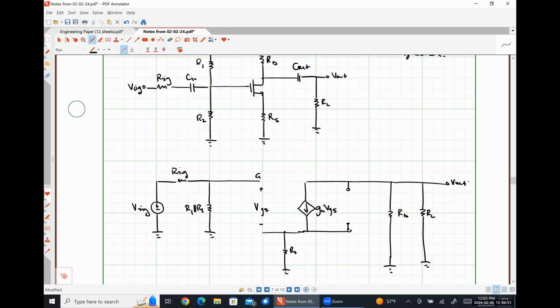I think it did immensely. So let me explain why I think it helped immensely. Because this would be the exact same as the small signal model for the BJT amplifier, except that RPi has now been replaced by an open circuit. So we can literally just go back to our notes for how the transistor amplifier behaves as a BJT and see what happens with RPi as an open circuit.